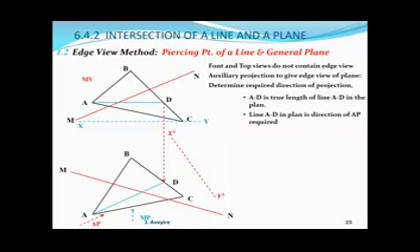So we select our first point of projection, auxiliary projection point C, and we project here. Now we have to look at that correspondence from our mutual view. The point C is exactly on XY. Therefore, we move along our projector from C, and that will be exactly on X1, Y1. Then we go for the next point, that is A, project A along the AP.